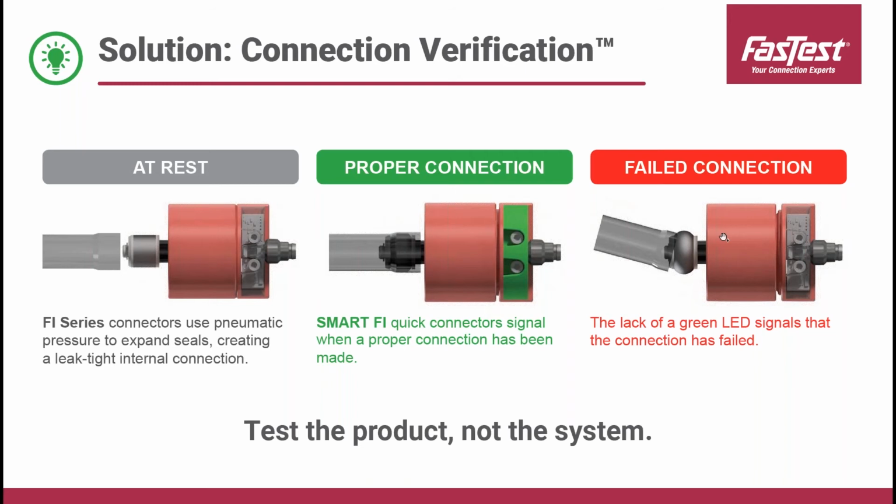So connection verification provides a check on your system and all the connections that are attached to the product before you start the leak test. And that's the inherent value that it provides. Instead of getting false failures and retesting and troubleshooting different products and systems and engines, you know that your connections are good before you start that test.